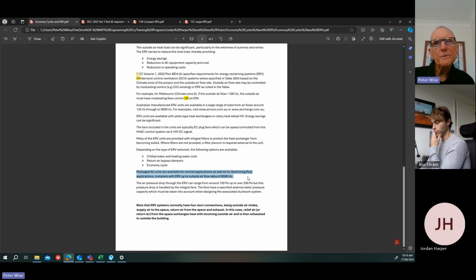And when I mention swimming pool applications here, I mention that specifically because quite often you guys will do a pool air conditioning system. And pools, as you know, generally the larger pools have chlorine in them. Chlorine is very corrosive. So you have to be careful with the materials you use for ductwork, and anything that the air comes in contact with has got to be corrosion resistant. So these swimming pool packaged air conditioning units are made with stainless steel. So they're resistant to the chemicals in the air.